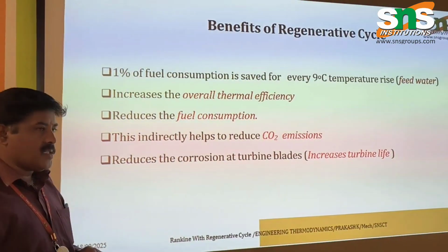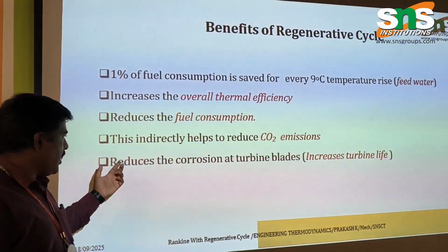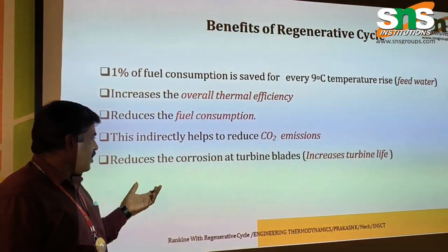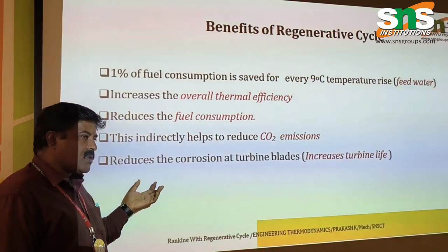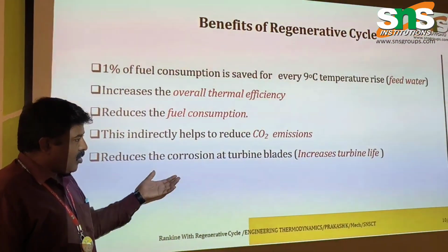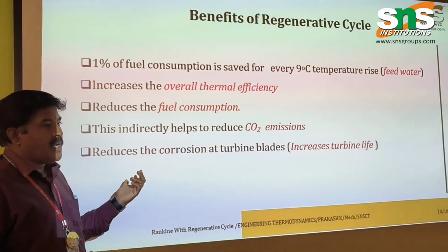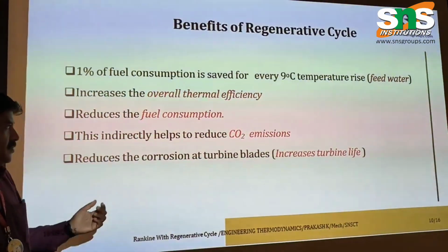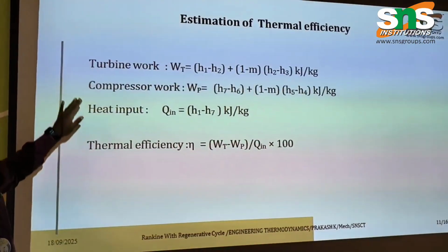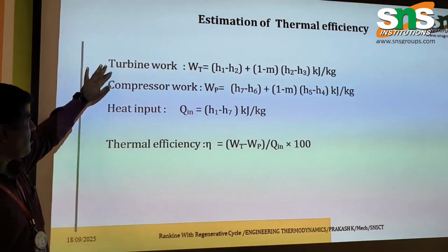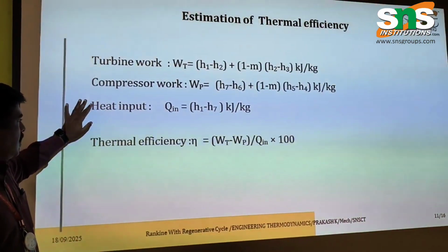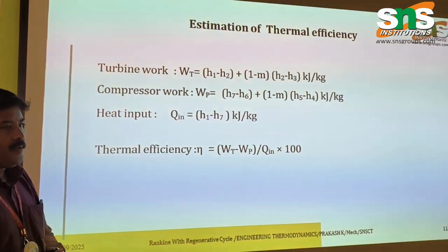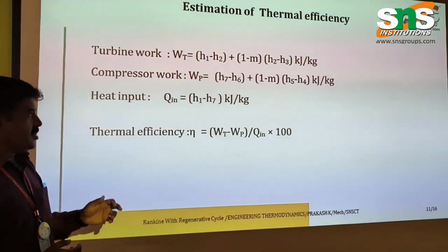It not only reflects in our profit but also indirectly reduces the CO2 emissions. And as the water is getting heated, the corrosion of the turbine blades will not take place, so it increases turbine life. These are some of the things, and we can calculate the turbine work, pump work, heat input and thermal efficiency based on the enthalpy at the various stages.